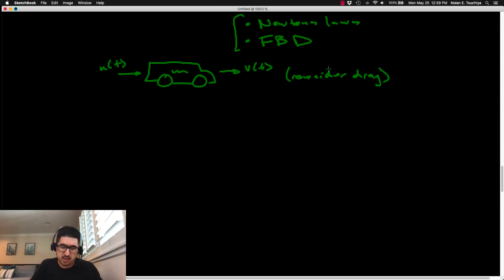Okay, so we want to model this system, which means we want an equation or a set of equations that describe this system fully so that we do not have to rely on our intuition. Well, it's a mechanical system, so the first thing we want to do is to try and analyze all of the forces in this system. We only care about horizontal forces because we're talking about the horizontal velocity here, so that makes things a little bit easier. There's only one mass involved, and that's the mass of everything that has to do with the vehicle. We can lump into that mass.